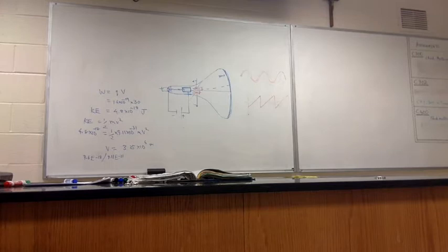Okay, this is the terminal where the anode is connected. Now, this is something that is dangerous to play with, because, as I said, the voltage is what? 20,000 volts on the picture tube. Between the picture tube and inside here is 20,000 volts. And of course, the circuits will have that. So if someone is not aware of those things, they will end up touching and getting a fatal shock.